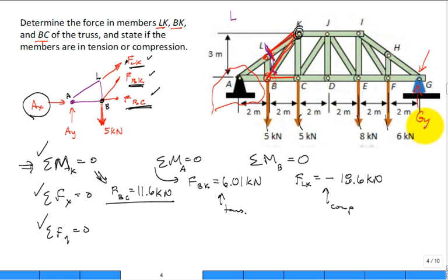Yeah, I would, to get A. First of all, if you do the free body diagram, AX is 0 on the whole truss. Now it's just AY, sum of the moments around G to give AY. All right. And I forgot to calculate AY and put it in. That was actually needed before I went to the method of sections. Thank you for that reminder. Let's press forward.